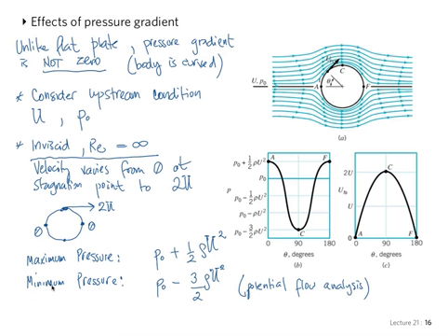But you see that what I was trying to illustrate in this discussion is this situation, which is that the pressure varies from a maximum value at the stagnation point to a minimum value at the point of 90 degrees and back to a maximum at the stagnation point if we follow that streamline that's right on the cylinder. And the velocity, on the other hand, varies from a minimum at the stagnation point, in fact 0, to a maximum at the point of 90 degrees and then back to 0 at the back stagnation point. This is all the inviscid case.